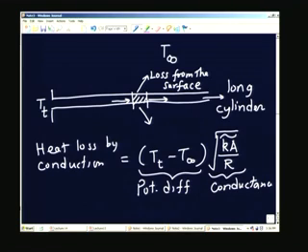So, what we should notice is that the heat loss due to the wire which is attached to the object whose temperature I want to measure is given by a simple formula. If this heat transfer comes from somewhere, that amount of heat transfer from whatever the thermocouple bead is attached to, the amount of heat it acquires must be exactly equal to the heat lost by conduction.